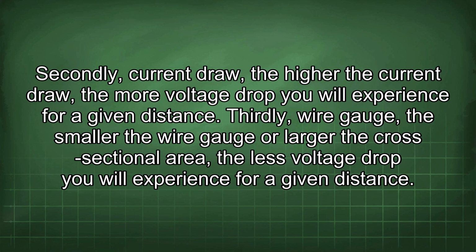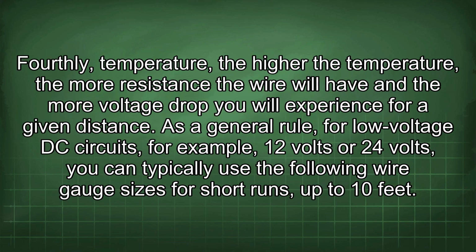Thirdly, wire gauge. The smaller the wire gauge or larger the cross-sectional area, the less voltage drop you will experience for a given distance. Fourthly, temperature. The higher the temperature, the more resistance the wire will have and the more voltage drop you will experience for a given distance.